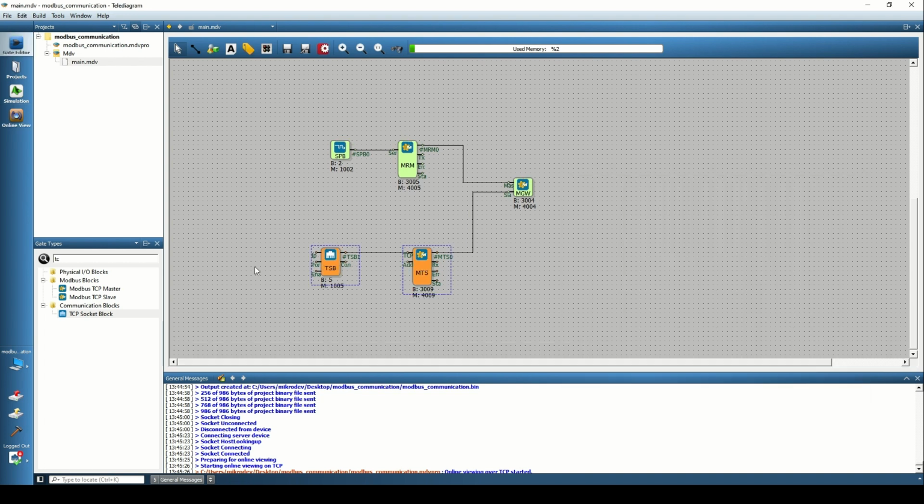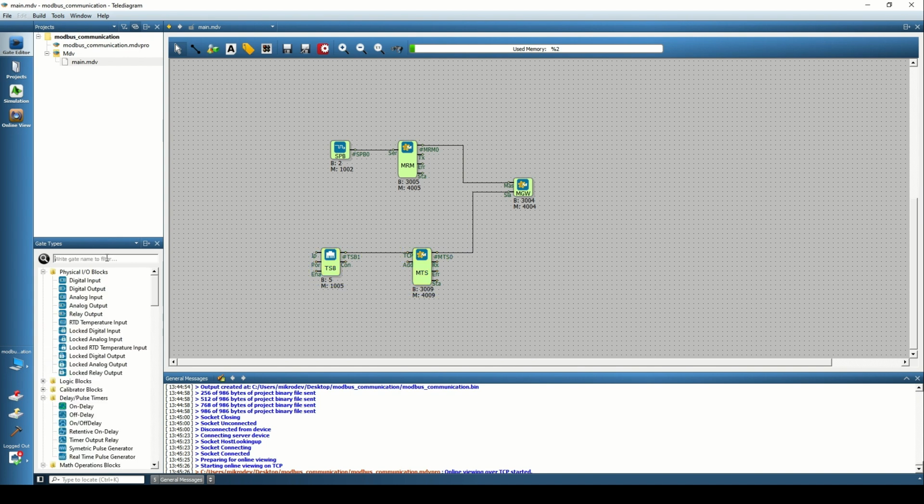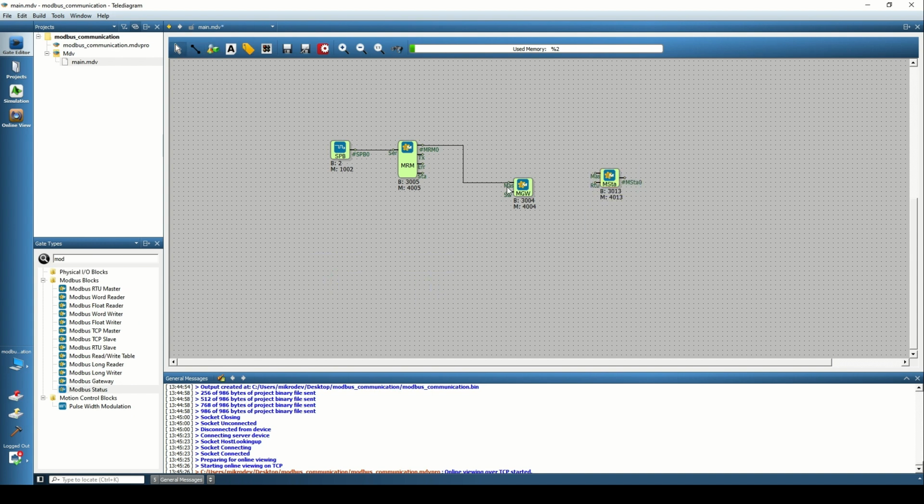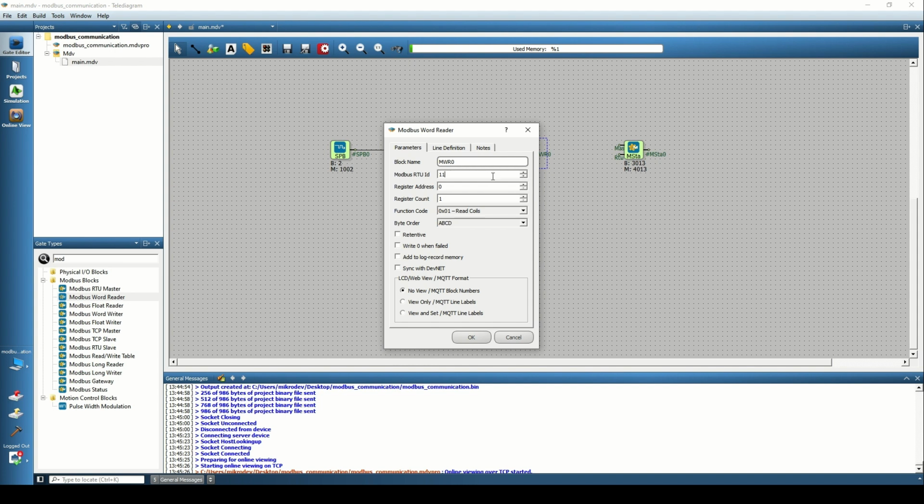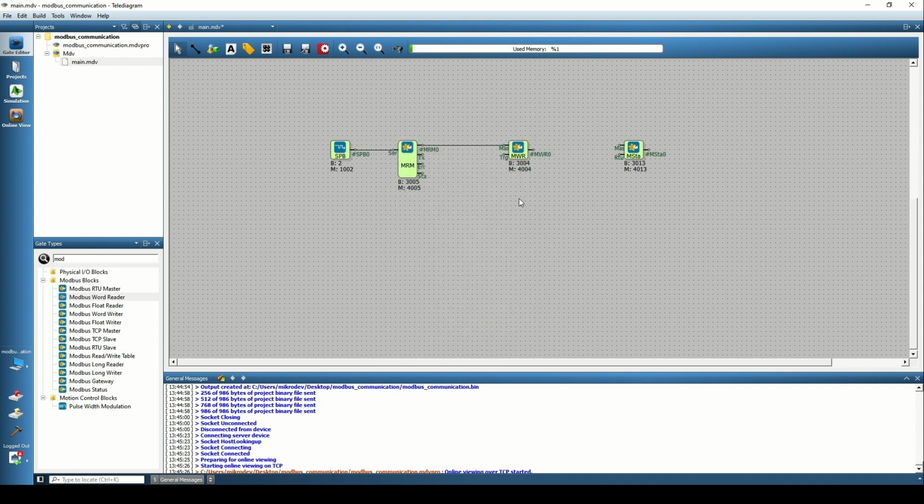Let's also talk about the MODBUS status. How does it work? For example, in a system where you connect via RS-485 port as a master, there may be more than one energy analyzer. Now, when we make examples, one of these energy analyzers may have a problem in the 485 connection or may have lost power. We learn whether it is connected or not via the MODBUS status block. Again, let's read data from device with ID 11 and data from device with ID 12. This time, we also connected the